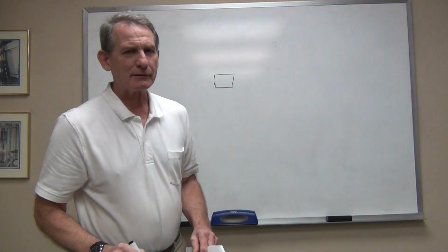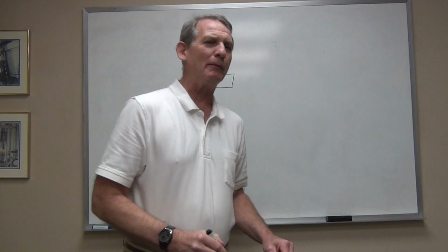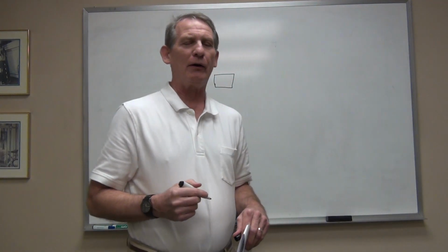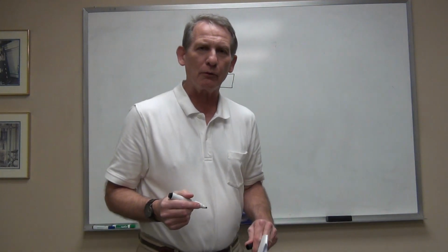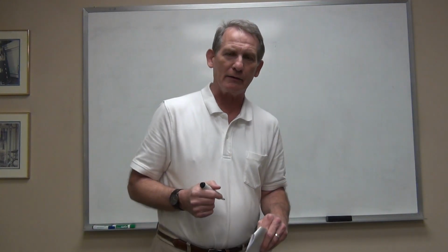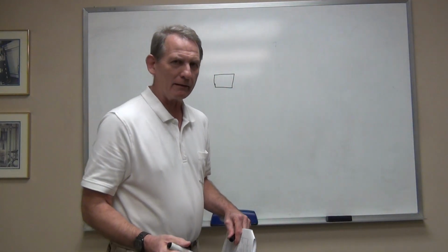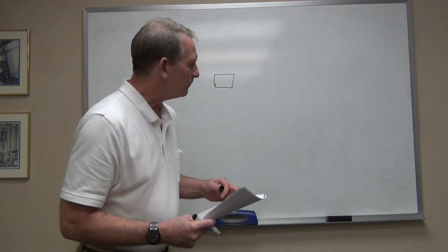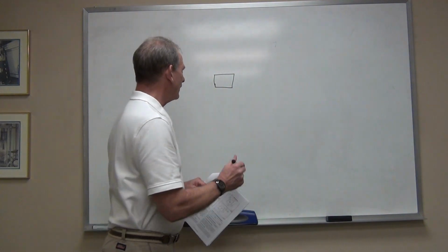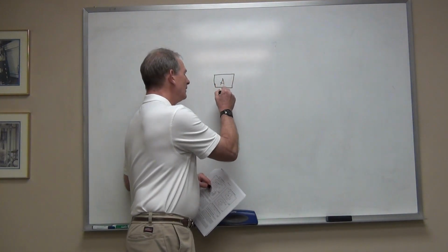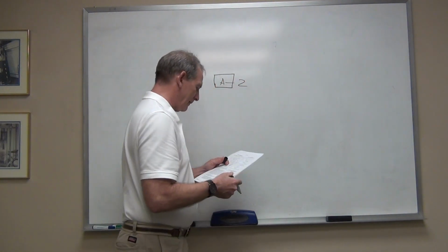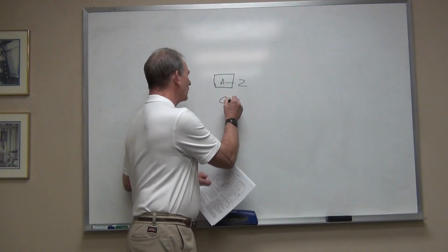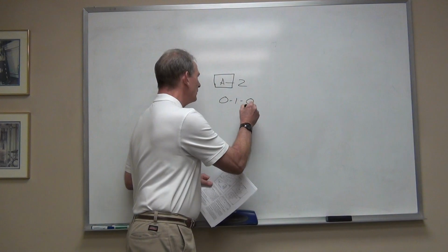And in that box, just like the feature control frame, one thing goes in there, and that is the datum identifier. The datum identifier will always be a letter. In the instance of this first datum symbol, in this box you will see a letter. It will be A through Z, and as I recall, you don't use O or I or Q.